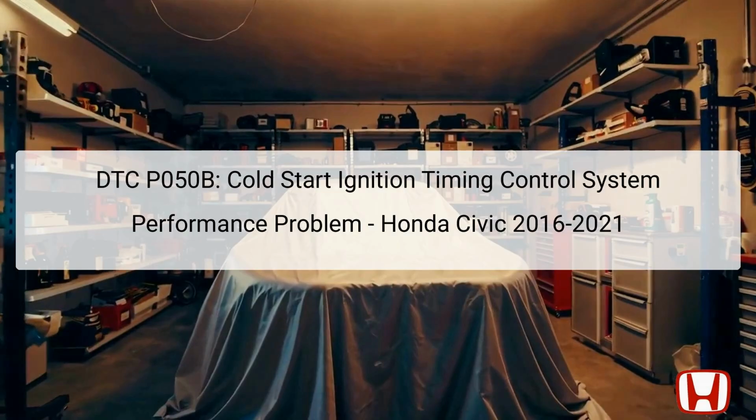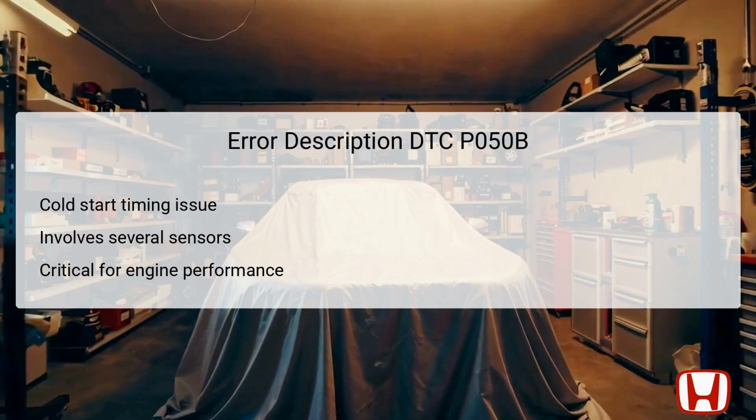Understanding and troubleshooting this DTC involves checking multiple components related to the ignition timing and air intake systems. Thus, a thorough diagnostic approach is required to identify the root cause of the issue effectively. The P050B error code represents a cold start ignition timing control problem, indicating that the vehicle's engine timing is not optimal during the initial startup phase.